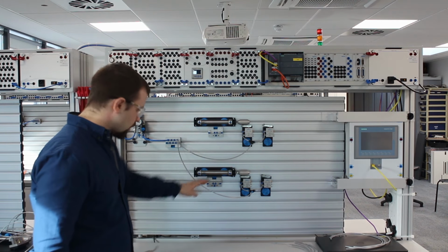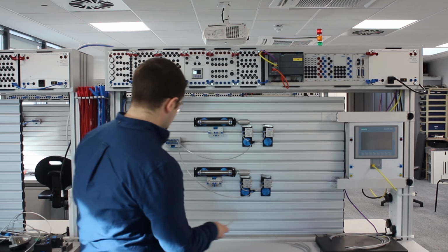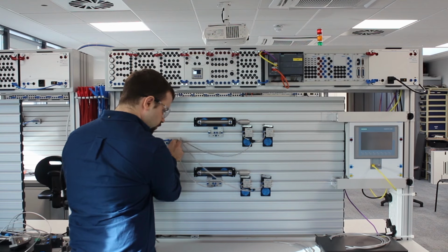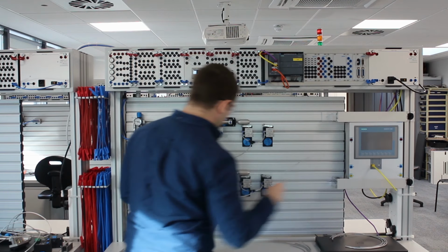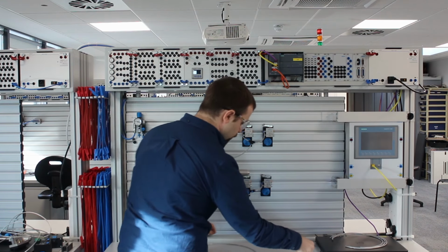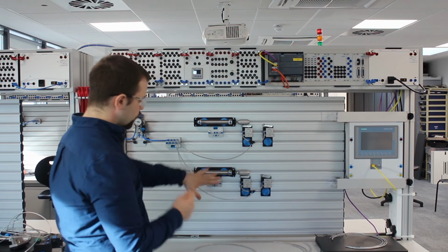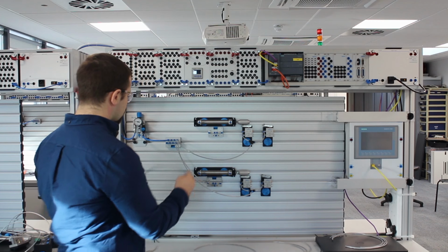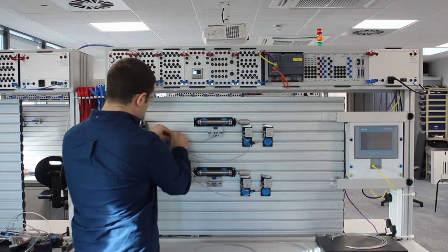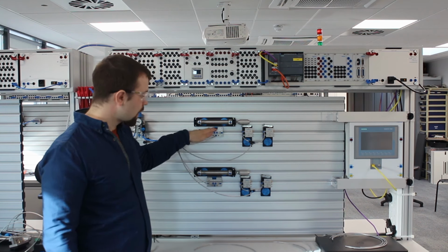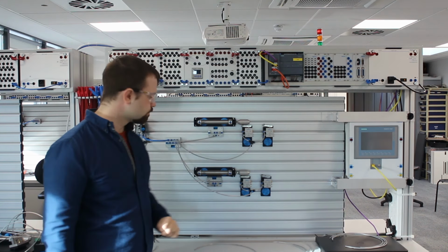Next, let's do our valves. We're going to need to use from 1 up to the manifold, and possibly one more as well. A shorter one might do. It's always good to try and use the shortest pipes you possibly can to avoid cluttering the board up. So let's go from 1 to here. There we go. So now our valves have power and also our switches.